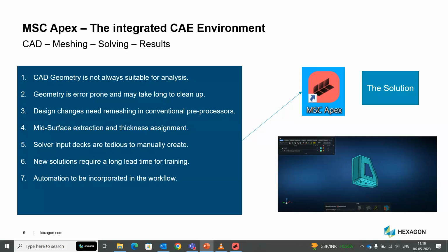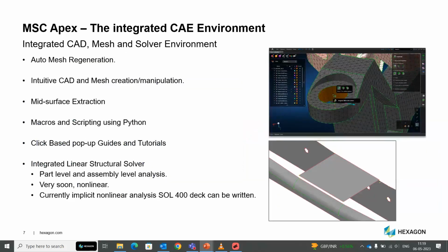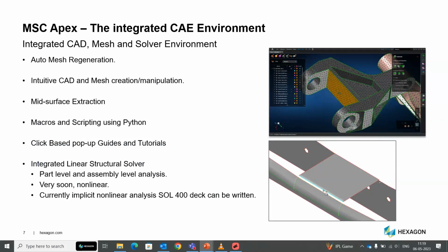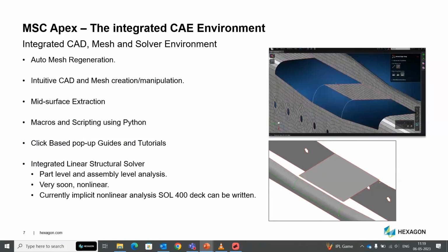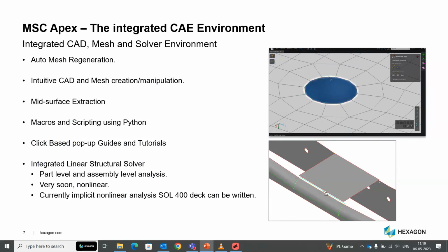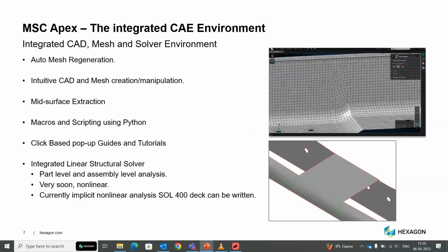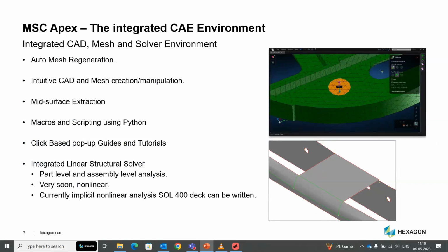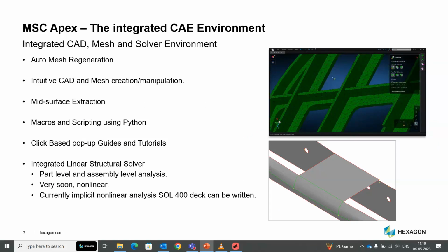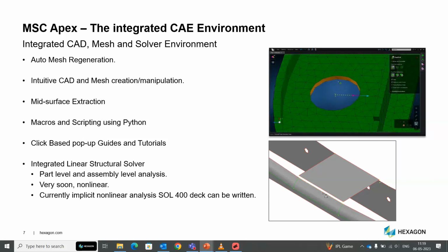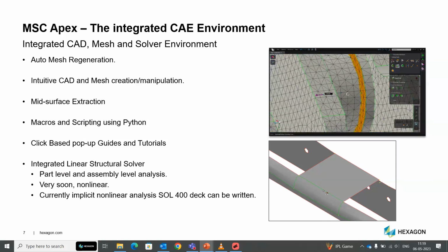So to answer all of this, you have a solution by the name of MSC Apex. So what is Apex? Apex, very simply put, is an integrated CAD, mesh, and solver environment, wherein you can manipulate the CAD, clean it up, make any changes, mesh it, and you don't need to remesh. As you can see in these videos, if you make any changes in the geometry, the mesh will automatically conform to it, and you'll be able to regenerate the mesh and then perform the analysis. You also have the ability to extract a mid-surface. Mid-surface is basically representing a 3D solid structure as a 2D shell element. That is also possible.